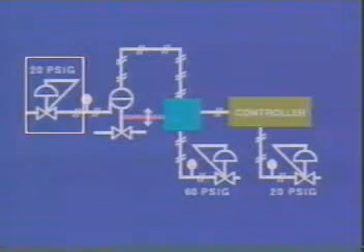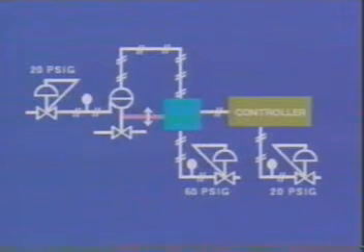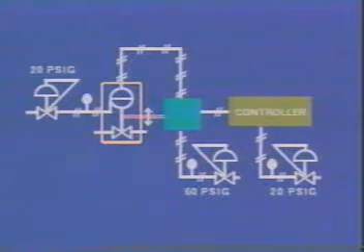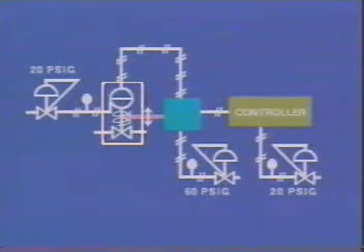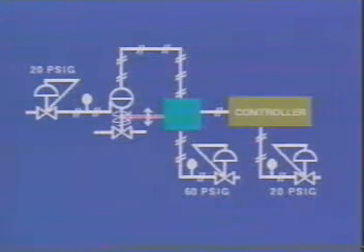In this system, a pressure of 20 psig is maintained on the bottom of the piston by this regulator, regardless of valve position. Now, for installations like this, consideration must be given to the fact that an air system failure may occur. In the event of such a failure, this actuator provides no fail-safe action. To provide fail-safe action, a check valve may be used to block air spring pressure. Another approach is to use an actuator design that includes a helper spring.